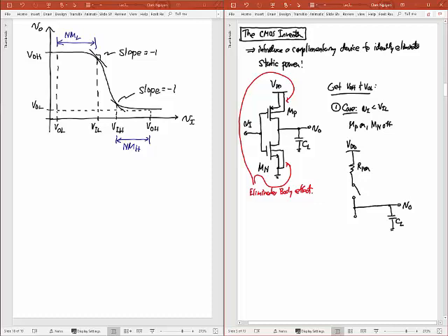And let me actually do it the way this is, because the PMOS transistor is on, which means that the switch is closed. It's shorting that out. But the NMOS transistor is not on. So it has its on resistance here, but it's open circuited to the on resistance. So R sub N on is here. And this then becomes my circuit. In this circuit, current cannot flow through that NMOS transistor down here. Ideally, there'll be no current flowing this way. All the current will come down from here, and we'll have to make a turn here into C sub L.